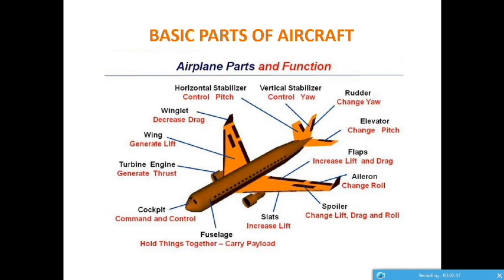It serves the purpose of reducing the speed suddenly. So if you have a problem of overspeeding of the aircraft, or you need a sudden emergency landing and your speed is not set to the landing speed, then you need to extend or deploy the spoilers in order to have a sudden change in the speed.